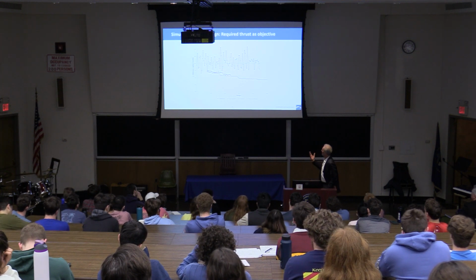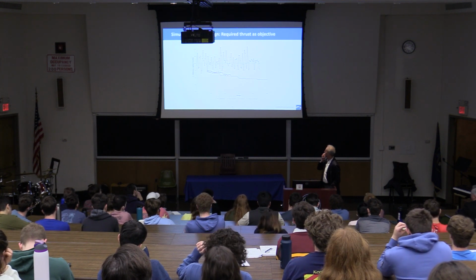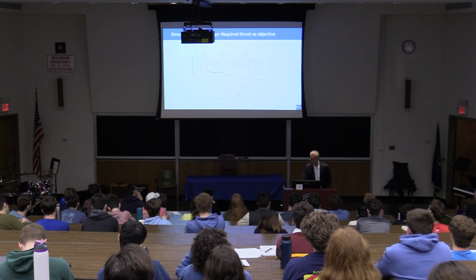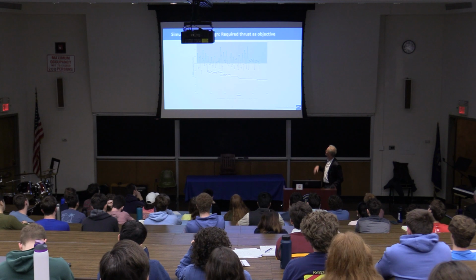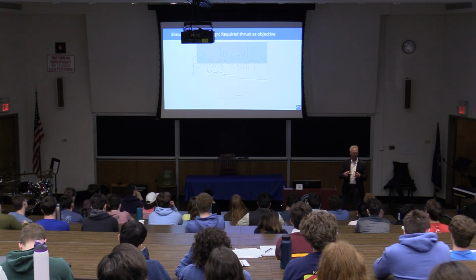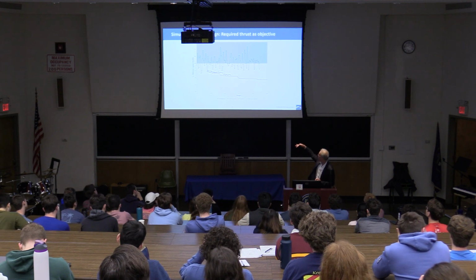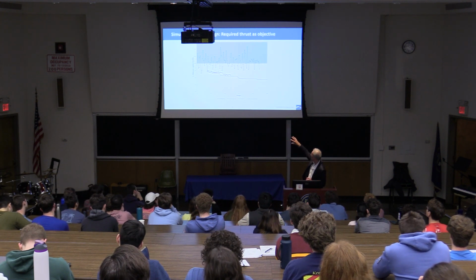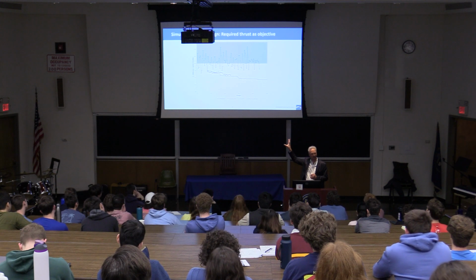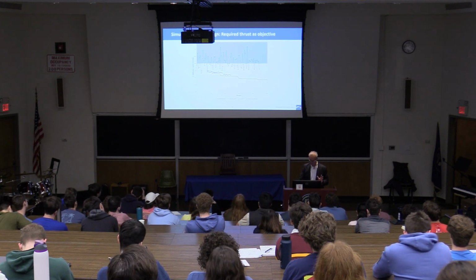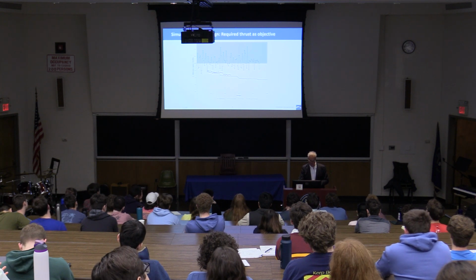A typical picture from a design of experiment, as I hope to have explained, is like this. Lots of designs in the blue region that are actually not performing quite as well as our baseline, but also, as you can see below the blue rectangle, everything that is a blue dot is performing better than the baseline. So we have an improvement already just from a design of experiment here of around 5%.